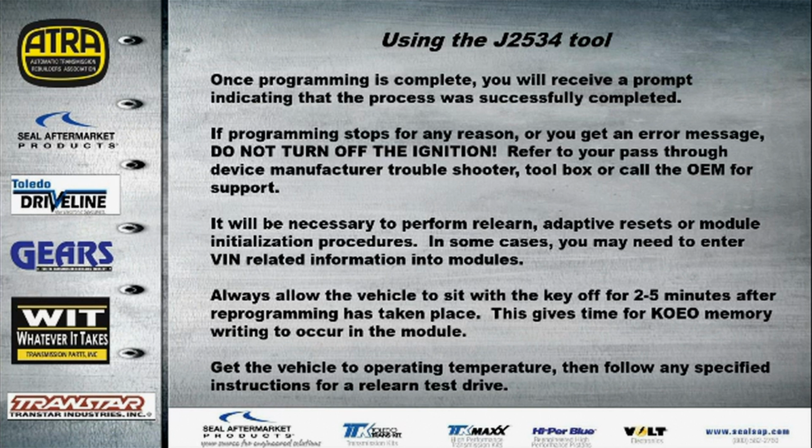Now, this is very much like flipping tiles. So, it's a process that happens when the key is off, and it doesn't seem like anything should be happening with the key off and engine off, but that's what happens with these modules. Just give them time to settle in, and then after that we can proceed to getting the vehicle to operating temperature, and then we're going to have any type of test drives that we have to do depending upon the make and model vehicle that we are working on.